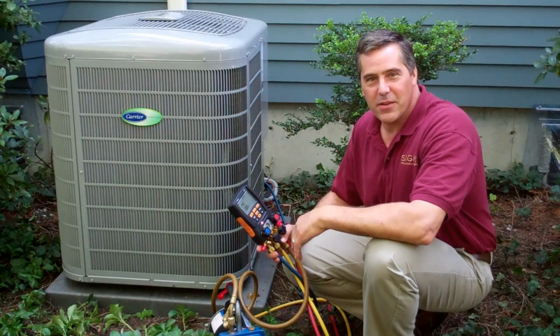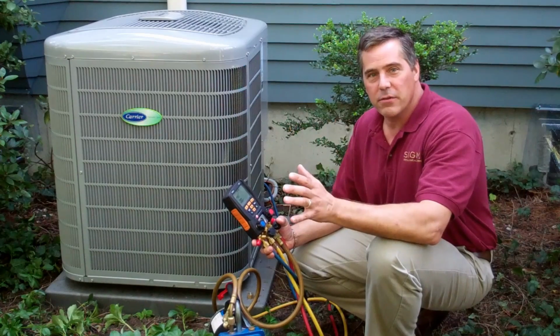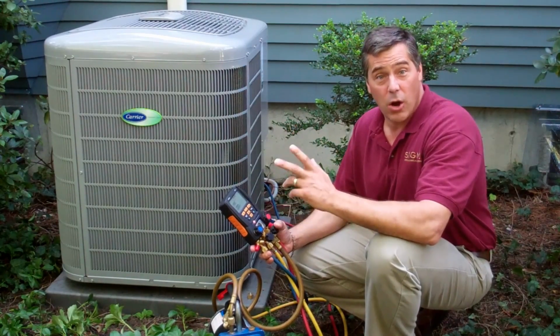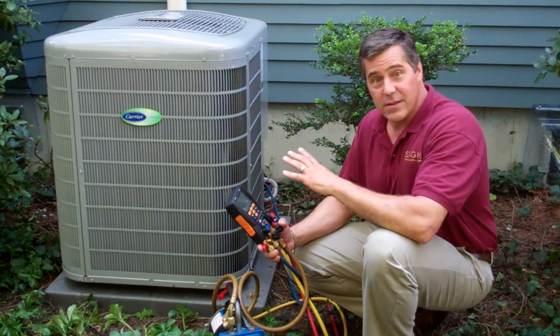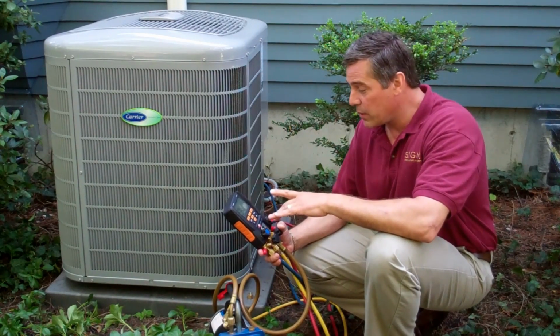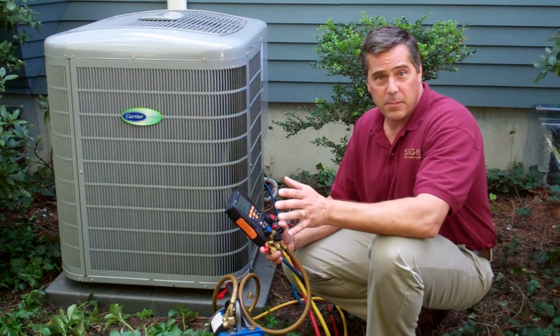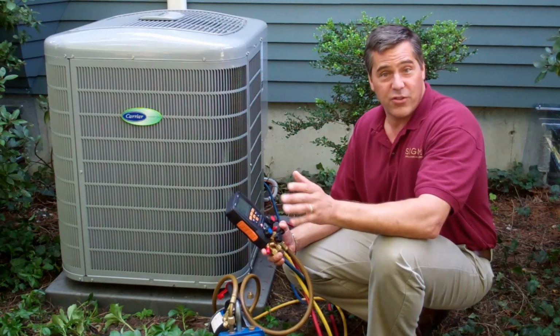Okay, this is my favorite part of the job. Everything's installed, the air handler's in place, the ductwork's in, all the registers are in. We've got our refrigerant piping done, our condensate piping, and we've also leak checked the system. Now we know it's tight. So the next thing we're going to do is pull in a vacuum. Once you pull in a vacuum, we know we get it down where we need it to be, about an hour and a half or so, then we're going to charge the system up.